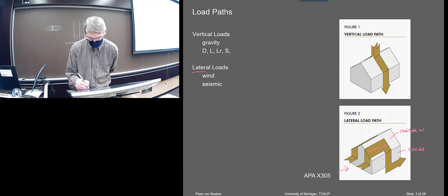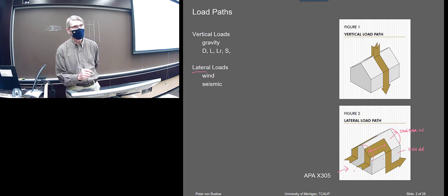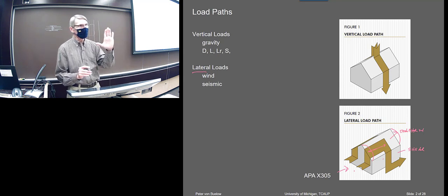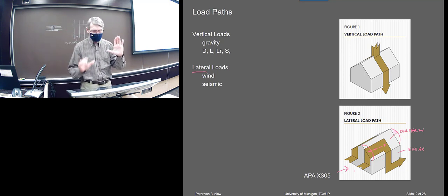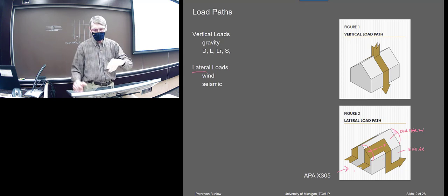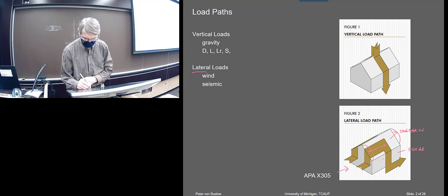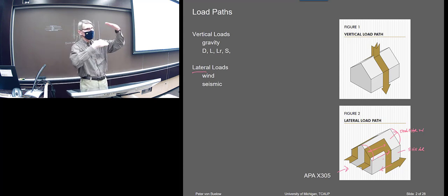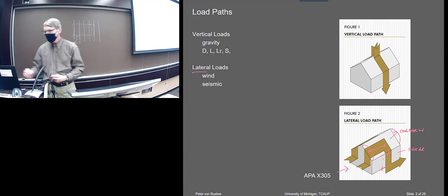If you see it as a very deep beam, maybe it's acting in flexure, but it's certainly picking up that push, and it transfers it to this in terms of shear, right? So the vertical part is really acting in shear.